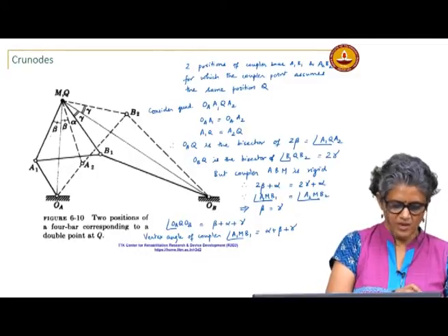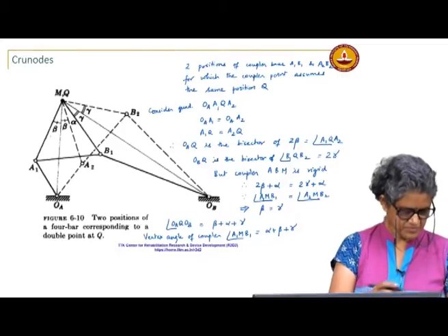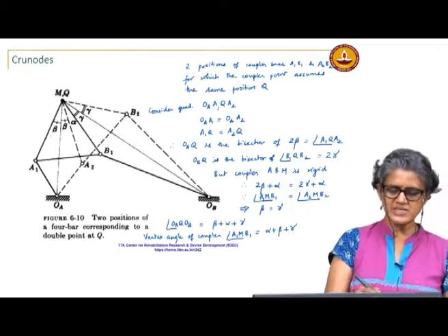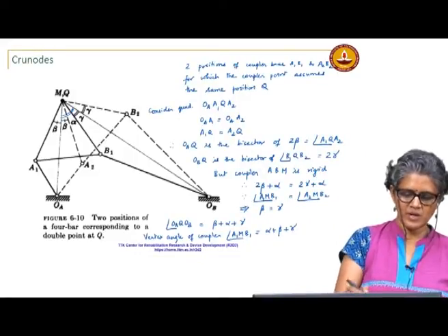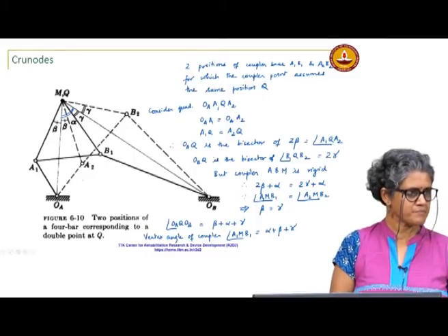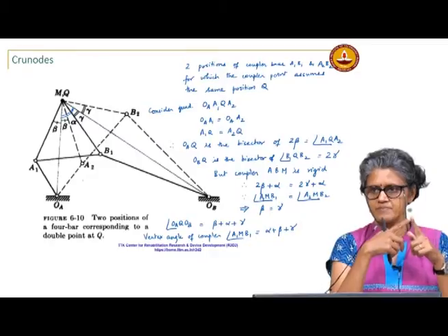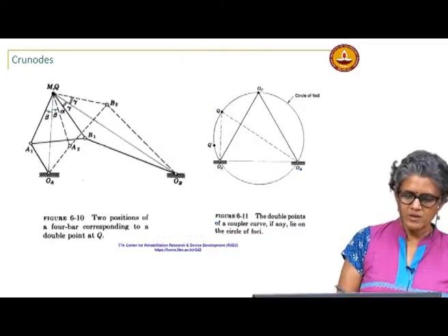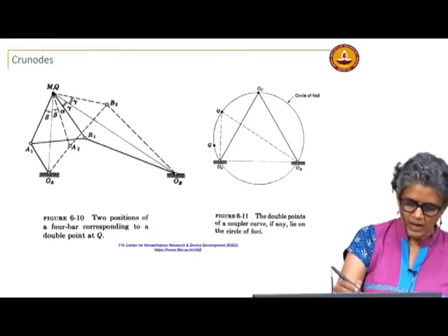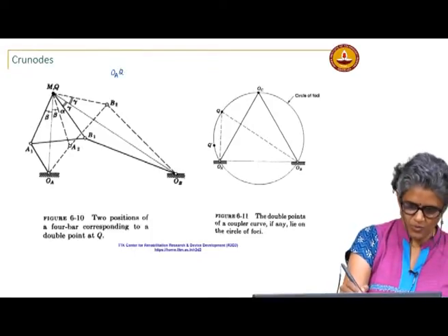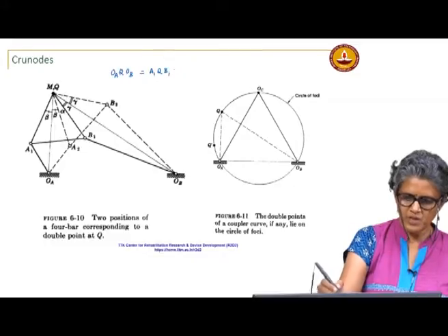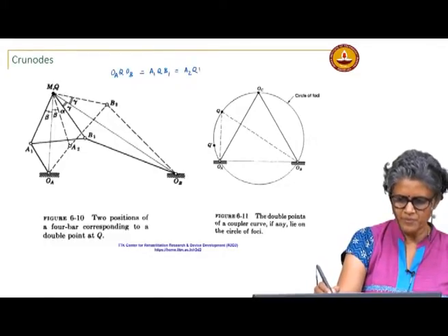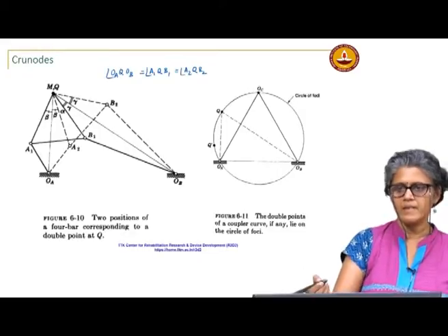So, this implies that this angle OA M OB is the same as A1 M B1 or A2 M B2, the coupler vertex angle at the point M. So, angle OA Q OB equals angle A1 Q B1 equals angle A2 Q B2, right, that is what I showed.